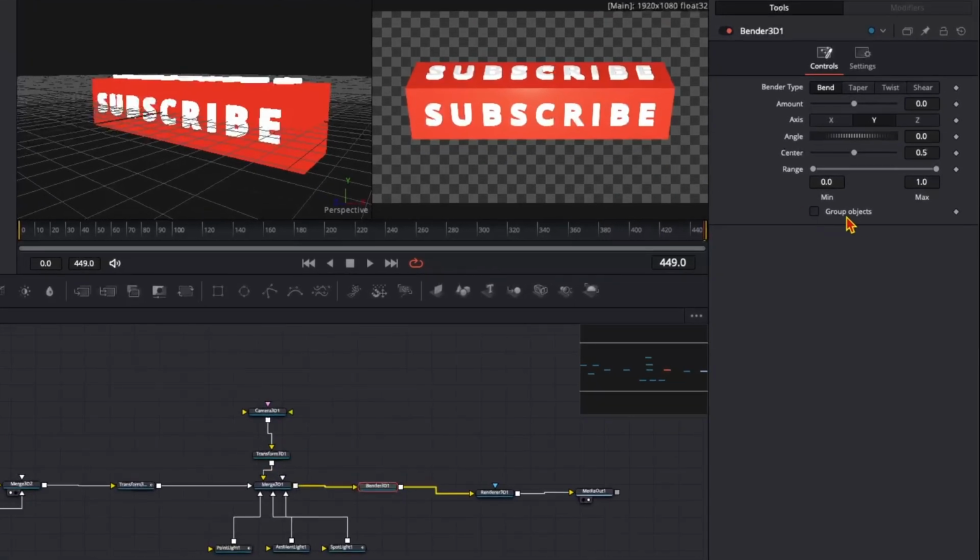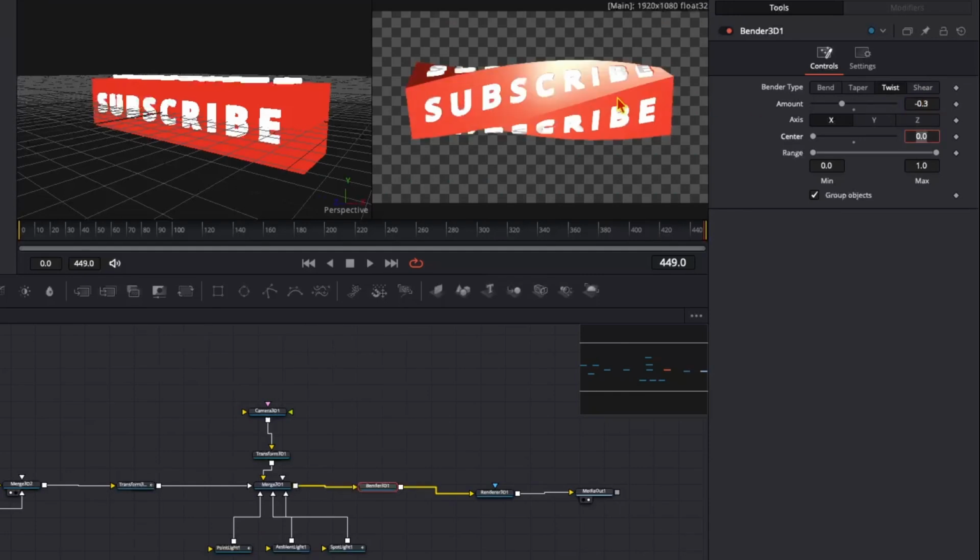First of all, we have to group objects because we want this bender 3D node to affect all of the elements, not just individual ones. Click the group object. Actually, we have to change the axis to X, change the center to 0, and now let's put the amount to minus 0.3. Now we have the correct bending on frame 0.